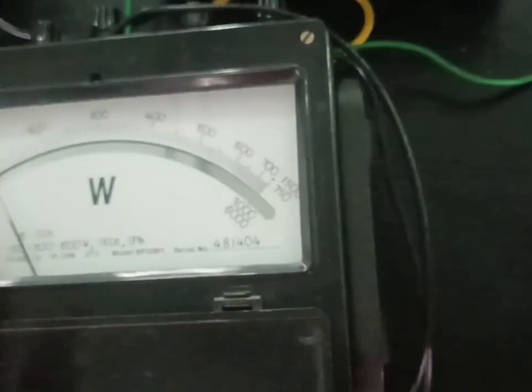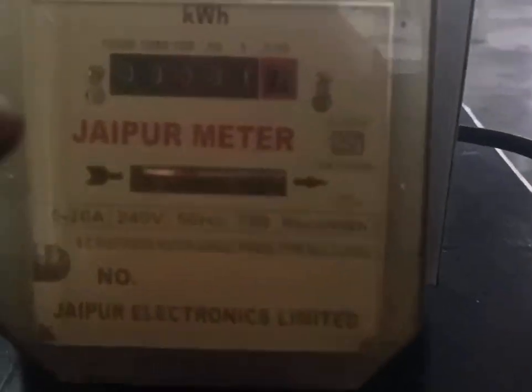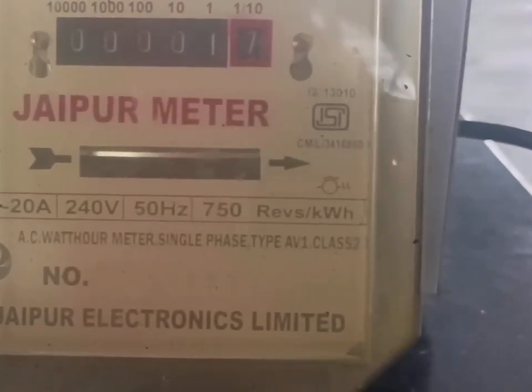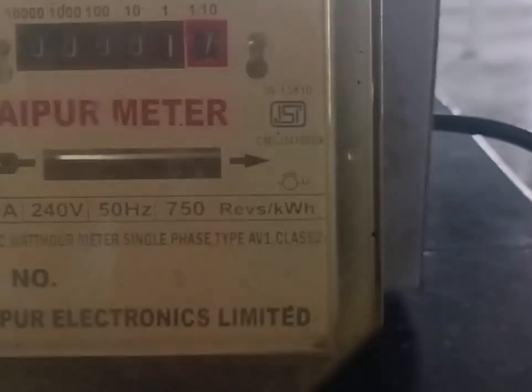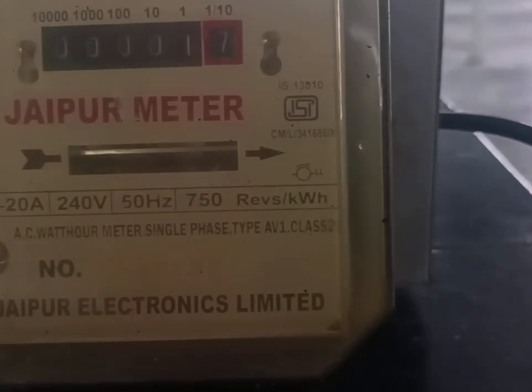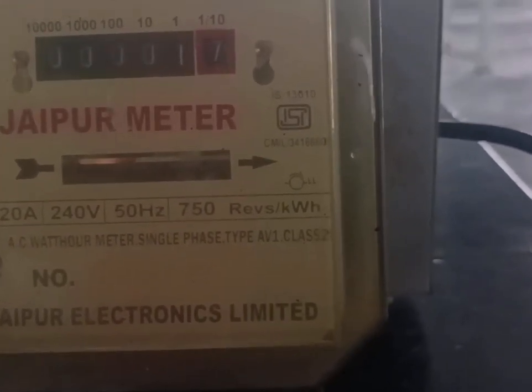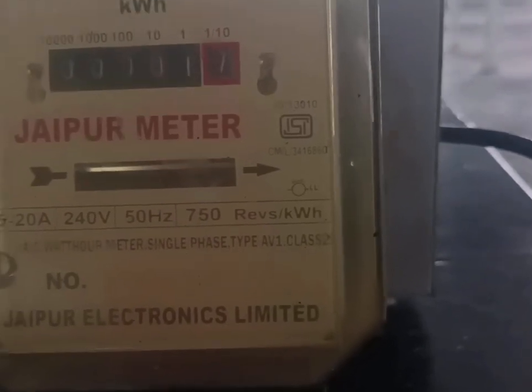The watts rating changes from 50 to 100, the ammeter shows nearly 2 amps, and the voltmeter drops another 1 or 2 volts. In the energy meter the disc rotations will be faster compared to when only the 1 amp load was switched on. Now the 2 amps load is on, and the energy meter disc will rotate faster. For this condition we have to take the second reading.